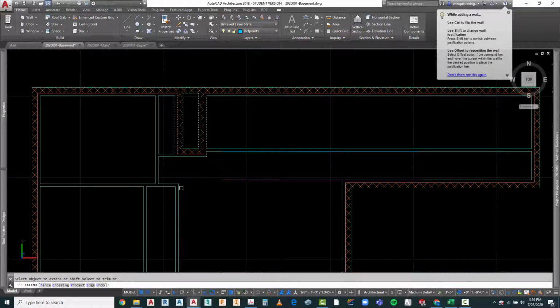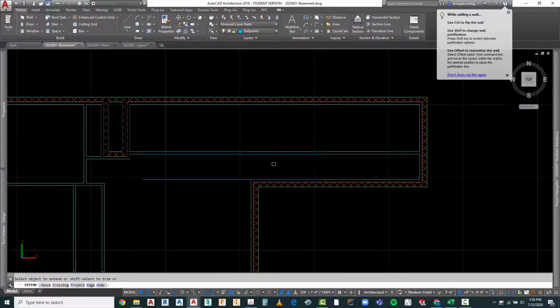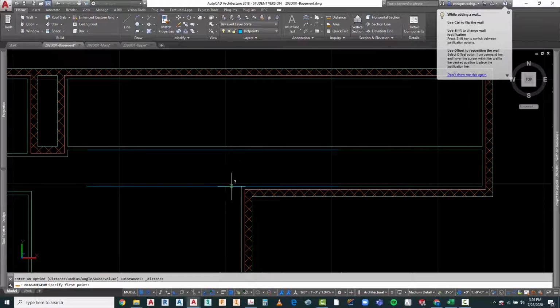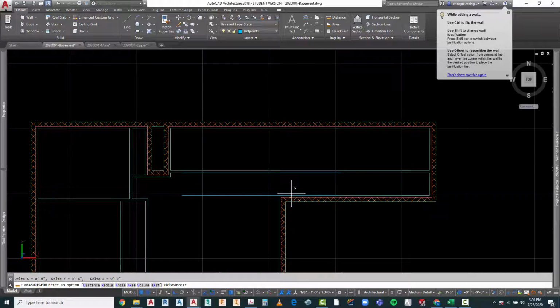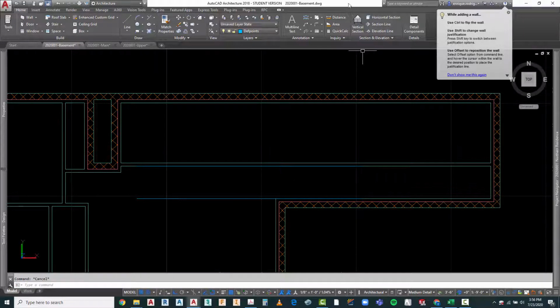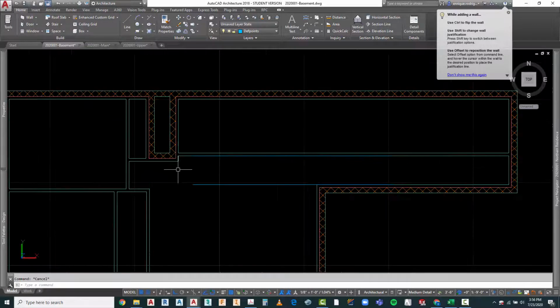A couple of things. This is a design solution, so it's something that if you're not quite clear on what you want in here. Now some of these older homes, and this is an older home, they don't need the 3'6" available in there. Maybe because they're going to be using a 2'8" door to get into bedroom 5 in here, and we only need 3 inches, maybe they only need 3'2". So let's do a compromise. Let's go ahead and move this down and give ourselves the 3'2" that we've got in there. And, okay, I think that would work.